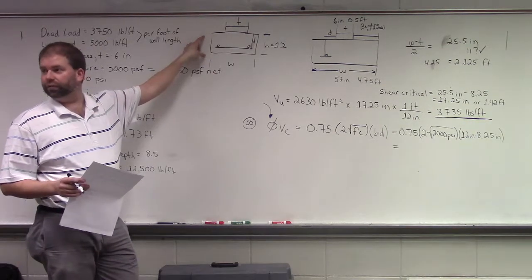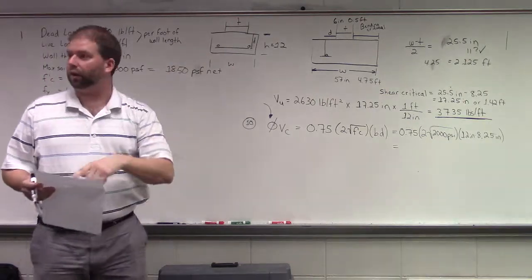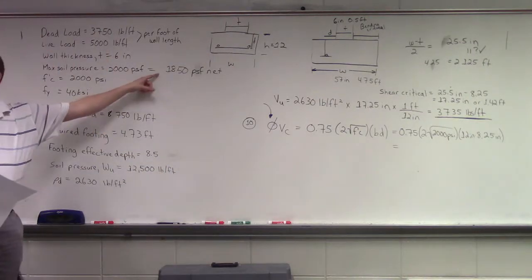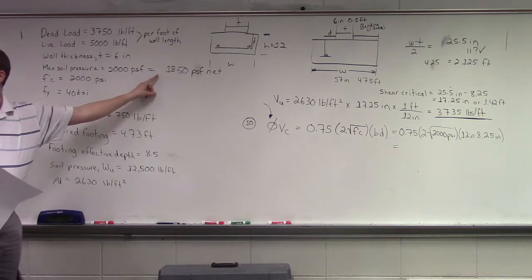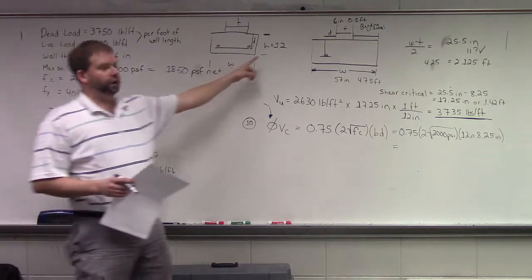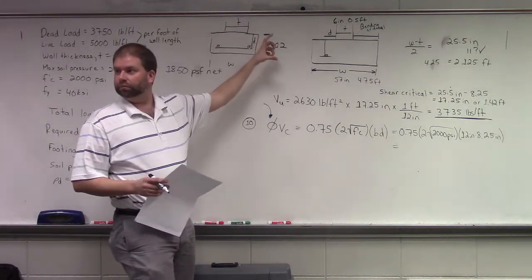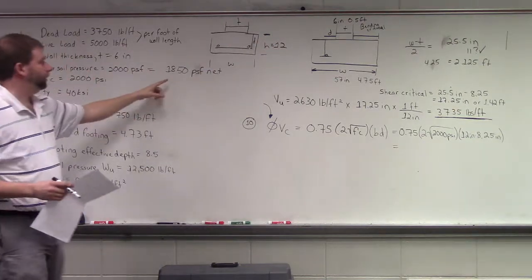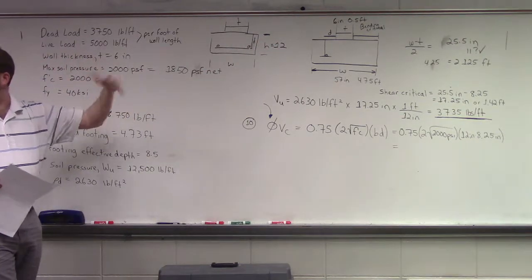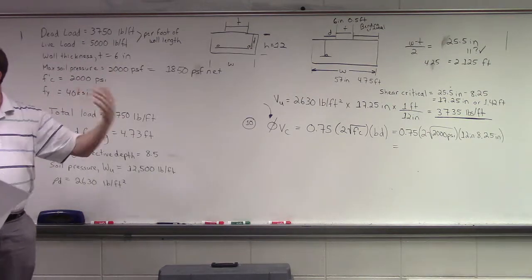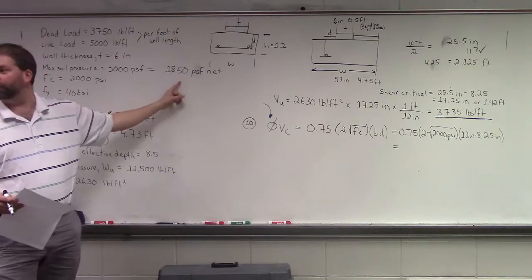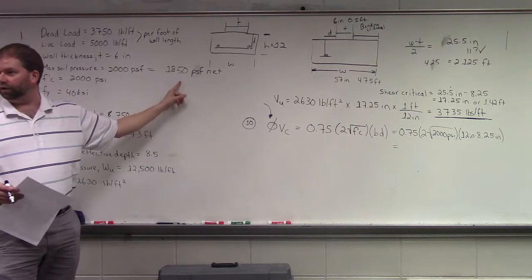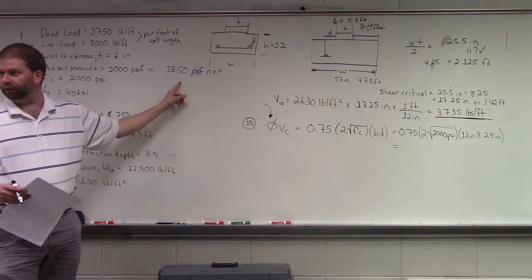The reason we did that is then we could figure out how much weight of the concrete is going to be exerted on the soil. If we use a height of 12 inches, and we were assuming normal weight concrete, so 150 pounds per cubic foot, that reduces to 150 pounds per square foot being exerted on the soil. So that's what that step is.